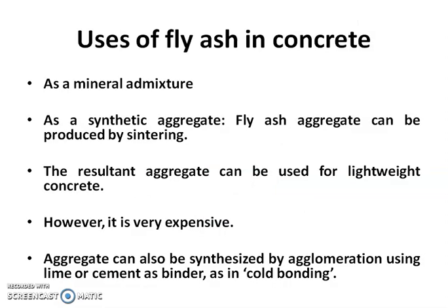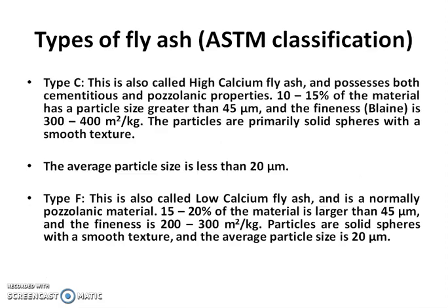So where is this fly ash used? It is used as a mineral admixture. It is used as a synthetic aggregate. The resultant aggregate can be used for lightweight concrete also. Aggregate can also be synthesized by the agglomeration process, and it can be used for cold bonding.